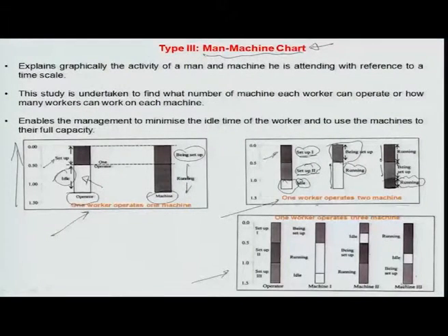That means setup being done together is avoided, and you can also give a time by time very nice sequence for the operator, so that all the 3-4 different machines which engage him completely are worked in parallel at different start points. Okay, so in this case, for example, in a 3 machine 1 operator system, you see that setup 1, setup 2 and setup 3 indicate the setup times for 3 machines.